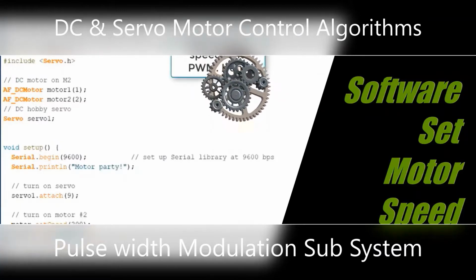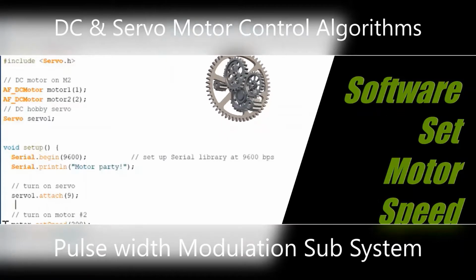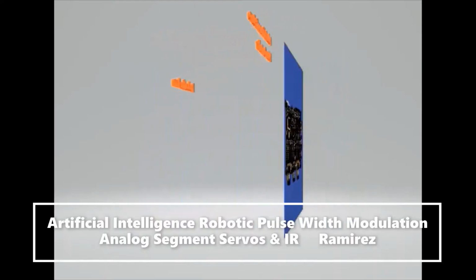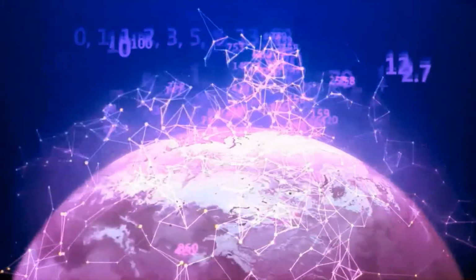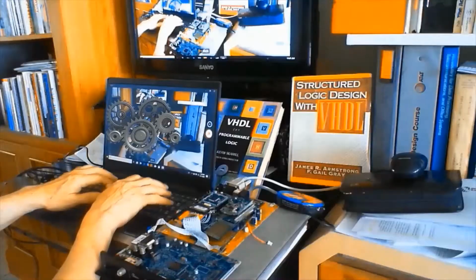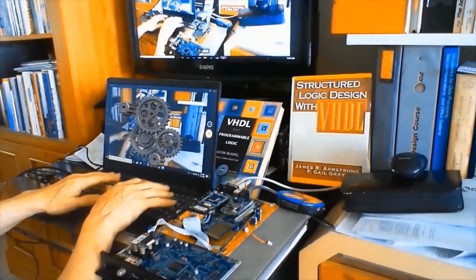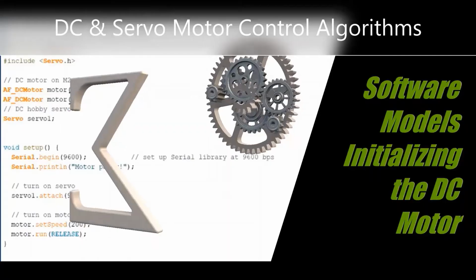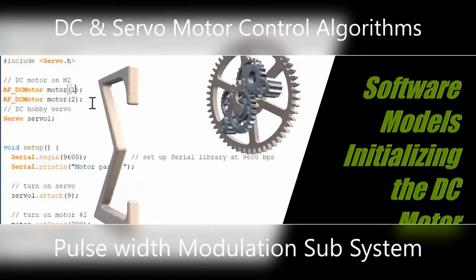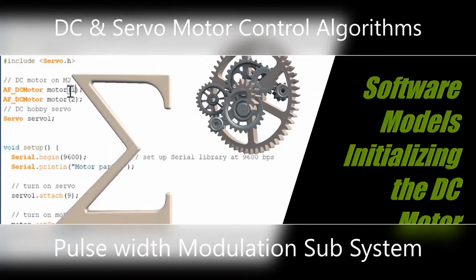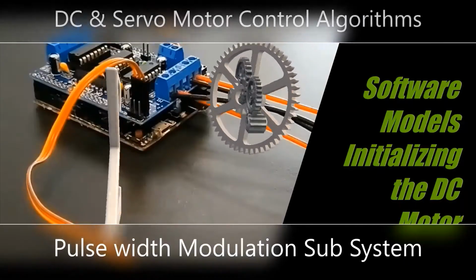The last parameter specifies the stepping style: single, double, interleaved, or micro-step. The step function is synchronous and does not return until all steps are complete. When complete, the motor remains powered to apply holding torque to maintain position.